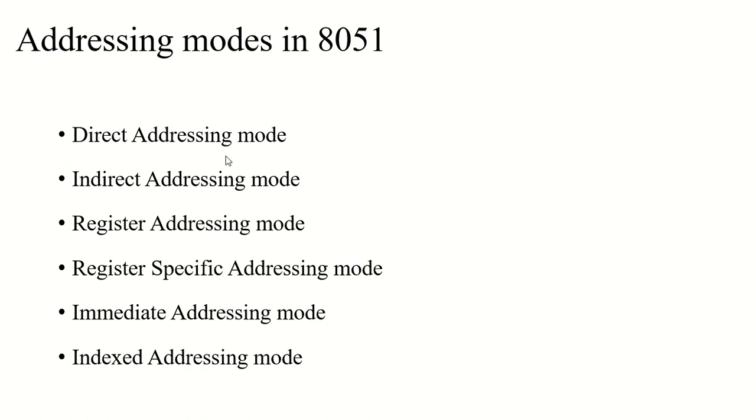Similarly, you can do the same thing with a register other than A, which means the accumulator. Let's say MOV R0, 14H. So what would it do? It would copy the content of the memory location 14H to the register R0 of the selected bank.